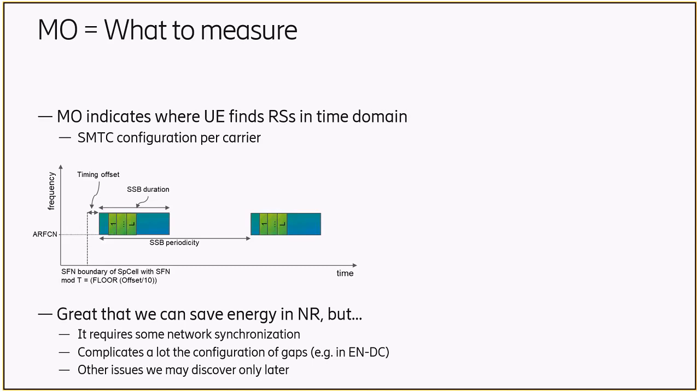Okay, sorry. Matthias was asking something about the figure here, whether the SSBs have to be packed into this blue part here. And I think the question becomes relevant, especially if you think of, let's say, the other nodes transmitting their SSBs. And everything has to be within the SMTC window, but the SMTC window duration could expand to multiple SSB durations. So they have to be synchronized, but they don't have to be transmitted at the exact same timing. So I can expand a bit. The whole point is it has to be within the window. Depends how long the window is.